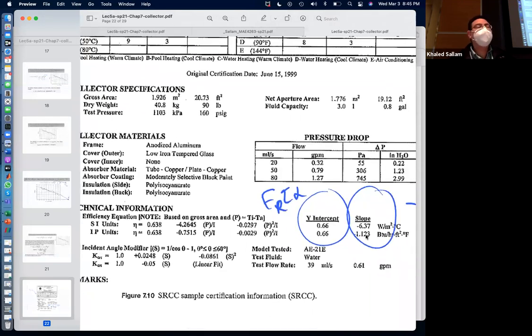You'd be tempted to think that they make the first order equation by just cancelling this and keeping the first two terms. No, the first order approximation is the same data, which is a little bit curved near the end, but they just want to put the best fit line that goes through all of them anyway. They do this a lot with heat transfer. People know that the equation is not linear, but they say, I just want a linear equation, to optimize the equation, for example. I just want a linear effect. So what? It's like 3% error, that's okay. Even within 10%, we are fine.